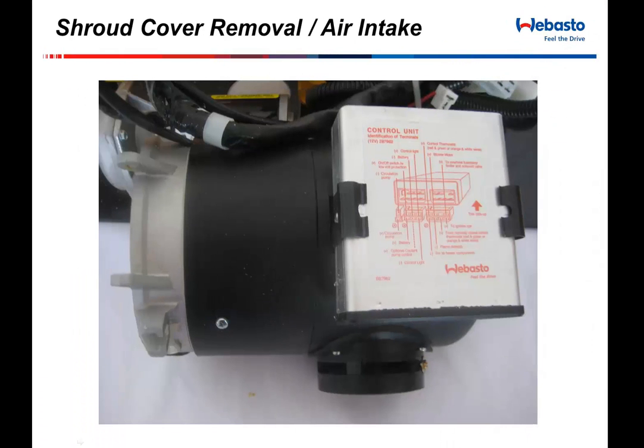You have the electronic control unit, which is again mounted right to the black shroud. On the bottom of it here is an air intake. These are all preset at our factory, and they are good to roughly about 5,500 feet altitude. If you are going higher than that, it may be necessary to open that up a little bit.